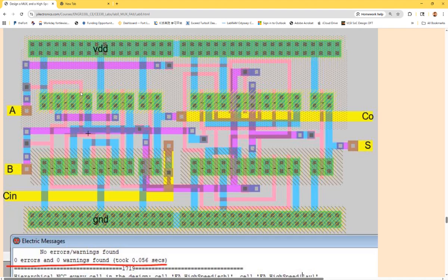and there are multiple ways to make the connection. You can directly place the via here and go to metal one, then metal one like a bridge, right, and go here and go down by one more level, down to poly again with a via, and then come to this poly. But you don't have space, so you got a metal one immediately next to it, and if you put a via here, it's going to have a DRC error. So in that case, you just have to use a poly to make the connection.